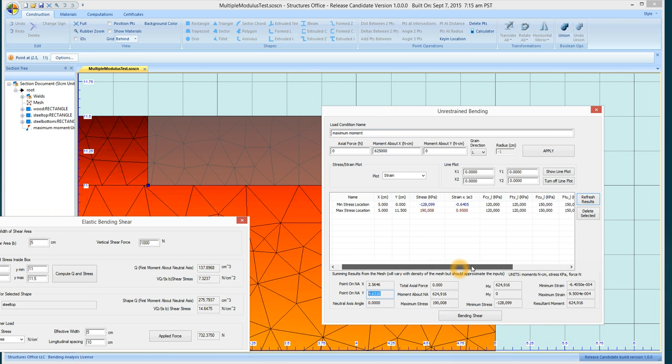And then if you're doing multiple materials, you want to use this number here to multiply that area. So you wouldn't want to calculate on an area that crosses material boundaries. That wouldn't work. So just keep aware of that, and I guess that covers bending shear stresses. Thanks for listening.